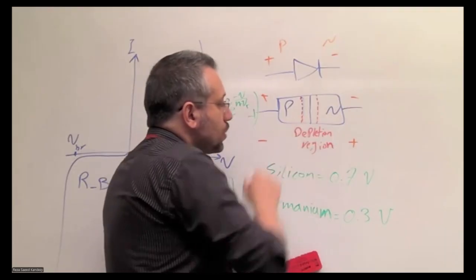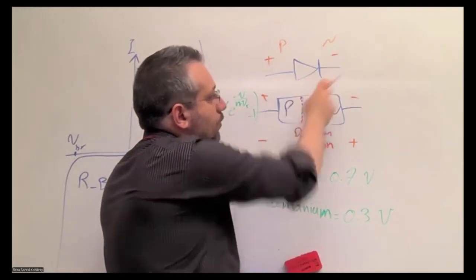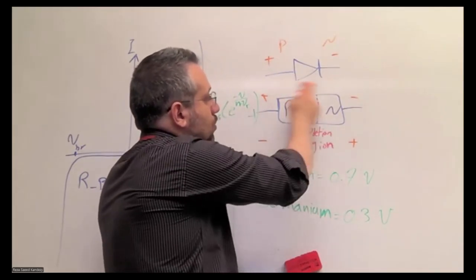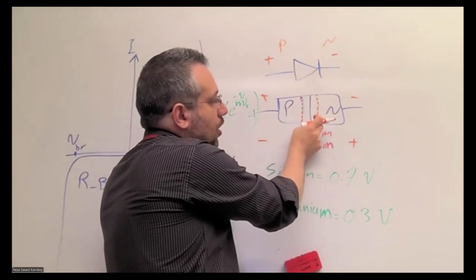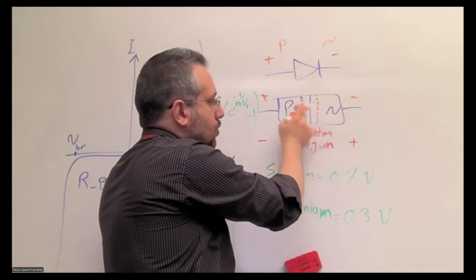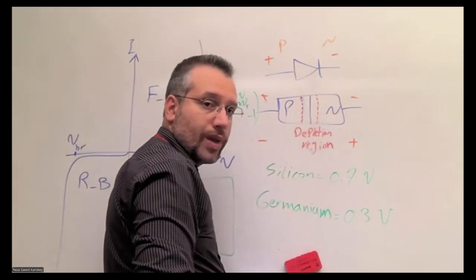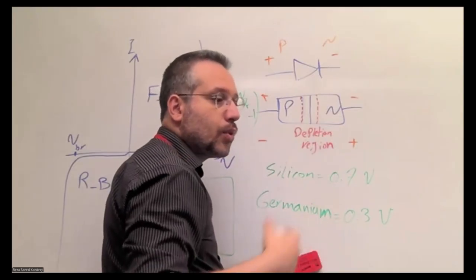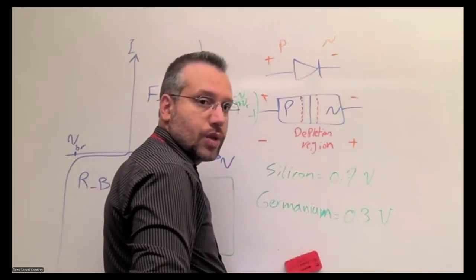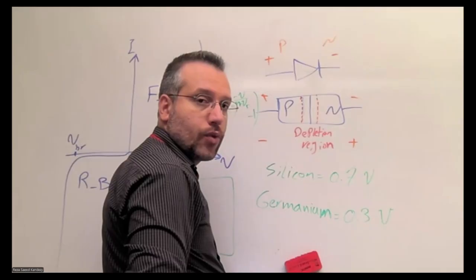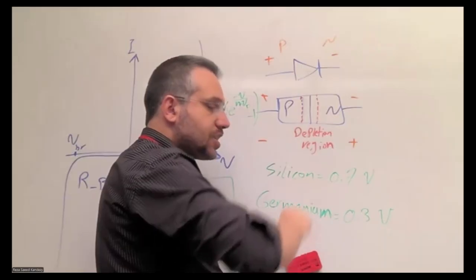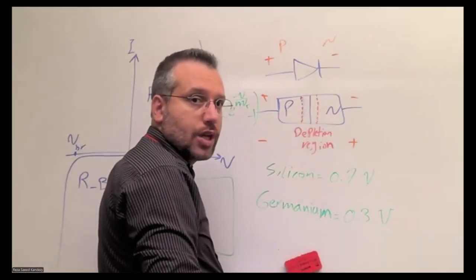Now we mentioned that by applying the forward bias, we need to increase the voltage across the diode until the depletion region is small enough so the charges could jump. What that means is that not just any positive voltage across the diode would create the condition for the charges to be able to conduct through the component. We have to exceed a certain level of voltage.